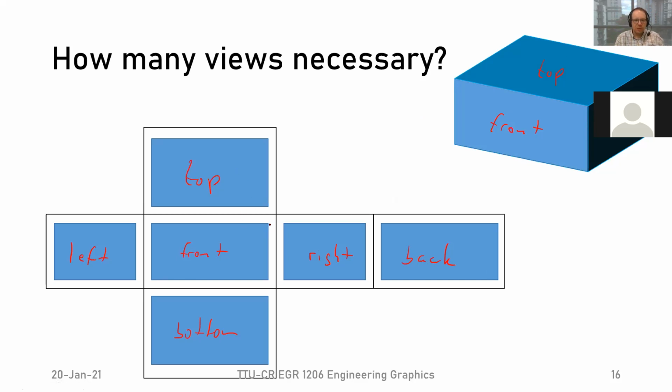We can say this one here, if we say that's our height, and if this would be our width, then that's all the information that we can get out of this one, right? But now from this one, we can get the depth, and of course, the width we'd see here as well, and so we can go from there. So these are the only ones that we'd actually need. So again, we were correct. The front and the top would be the only ones that we would need.